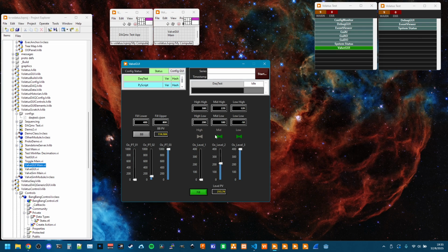And so this is going to choose which valves to use, what valve combinations to use based on this Ullage process value. And in fact, I just accidentally did it. If you go too high, which I have set at, I believe, 350, there's another set of ranges that I don't have on the GUI. But if I go above 330, that's right, it'll actually disable itself just as a failsafe. Maybe that's what you want, maybe not. It's configurable, but if it does go too high, it'll turn itself off.